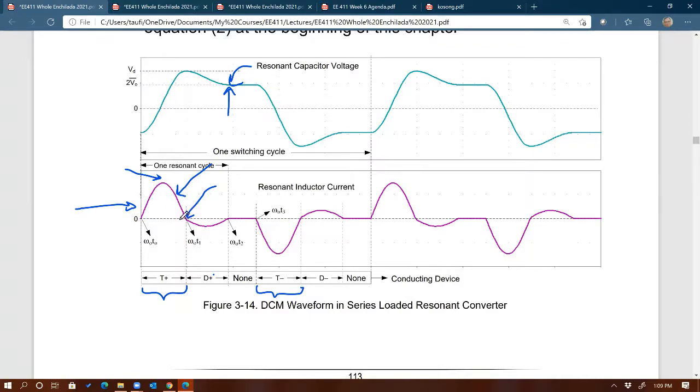So even if you are using a MOSFET, the diode will take over that negative current. So here is a good example where you can actually use a semi-controllable switch. You're not forcing the switch to turn off; the switch turns off naturally at 0 amps.